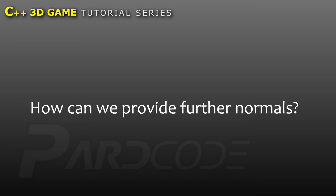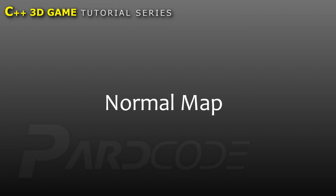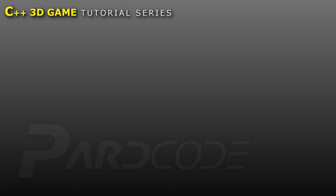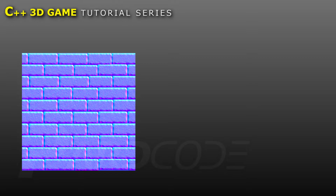But how can we provide these further normals to the lighting system? The answer is through a texture, in particular a texture called normal map. What is a normal map? As the name suggests, a normal map is a map that contains information about the normals of a particular surface, stored in RGB format. Let's see in detail how the normals are stored in the normal map.